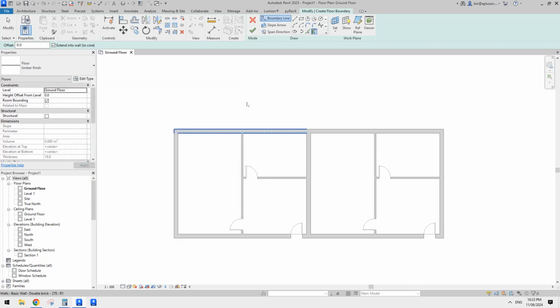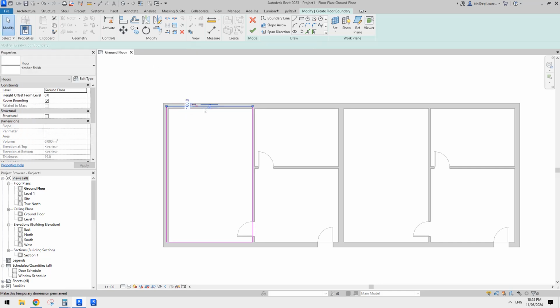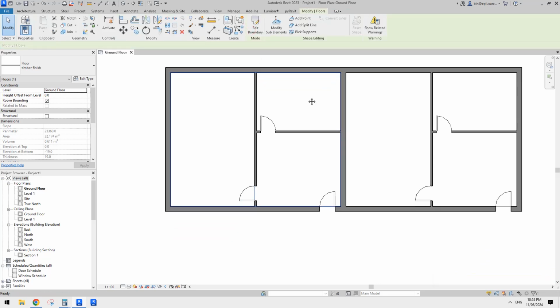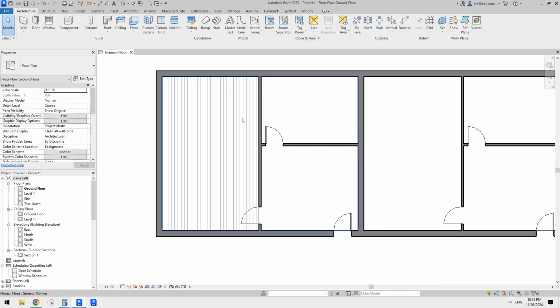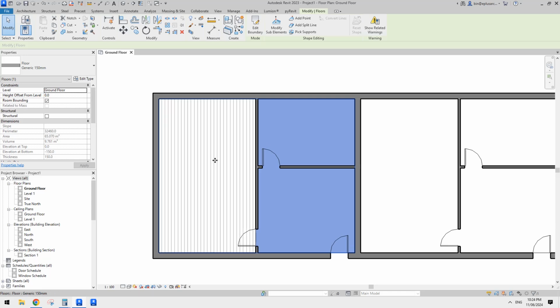And then for example, you can just pick walls, something like this, right? And then I think these need to be, oh hang on, yeah, that's great. Finish, and that's it. So Revit will give you a warning because currently you have two floors overlapping.